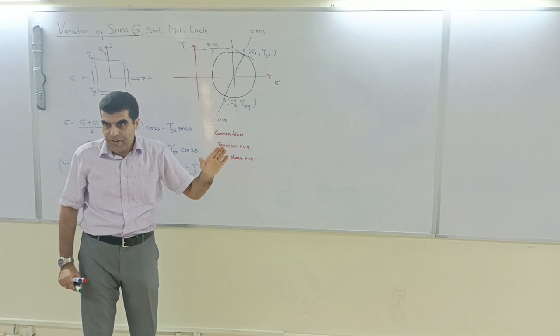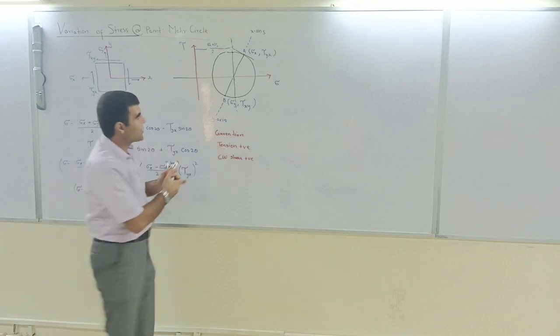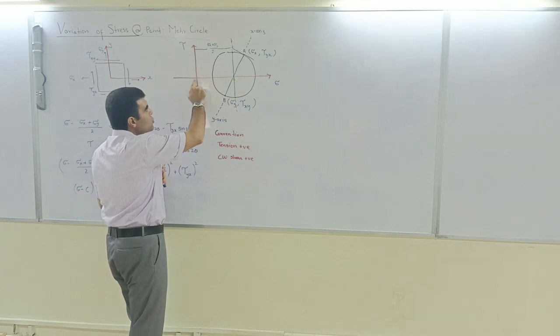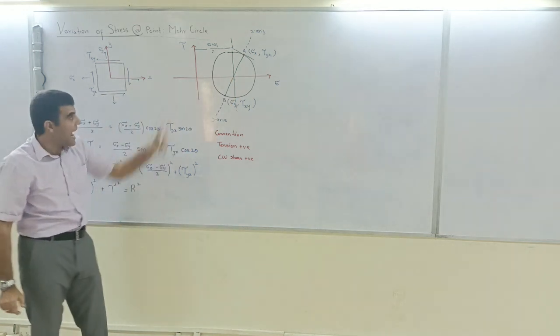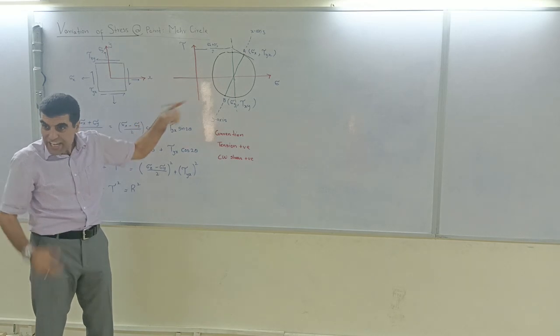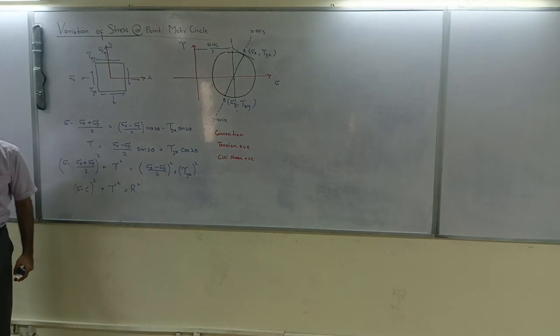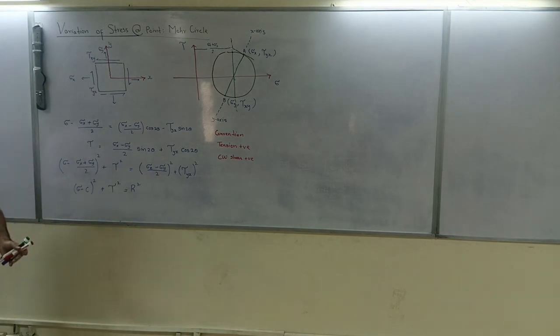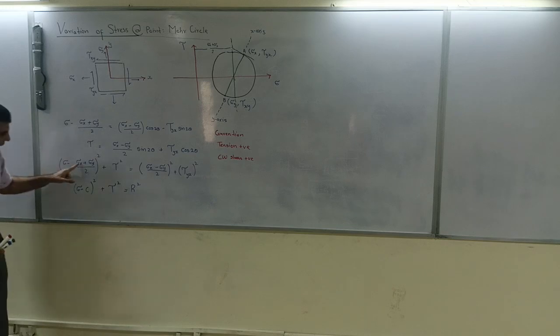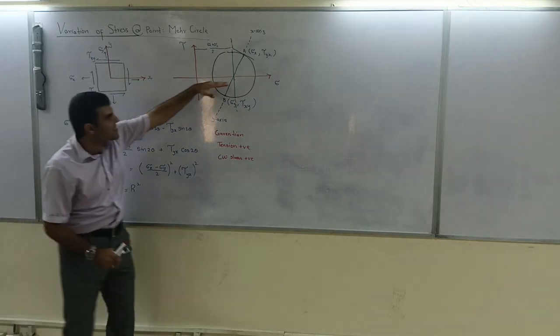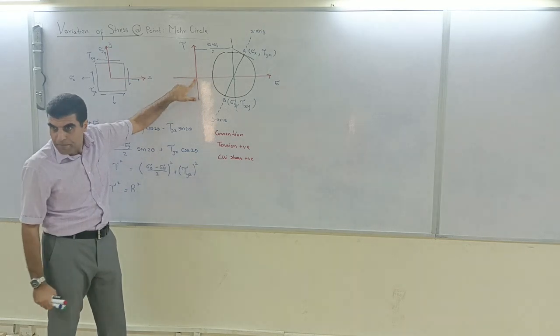What will happen if this Mohr circle which you drew came out to be over here at 0? When can you have that at 0? When stress x is equal to minus stress y. You can have any case. If your stress x is equal to minus stress y, these two will cancel out and your Mohr circle will come to this point.